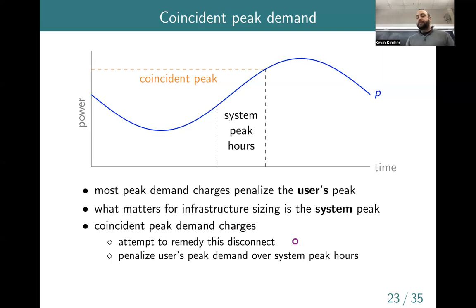Yes, that window may shift. And so again, this gets back to the fairness issue and the need for automation, because it's usually not clear very far in advance when these peak periods will actually happen. You may know maybe a day ahead, you may have forecasts of the whole grid demand provided by the system operator. And the system operator always knows how much capacity they have, how much transmission and generation and so forth. So that number is known. And if the demand forecast for the next day is really close to that number, then you might start saying, okay, I think tomorrow we're going to have a peaking event. So you might say, I'm going to be really careful about what we do during these peak hours.